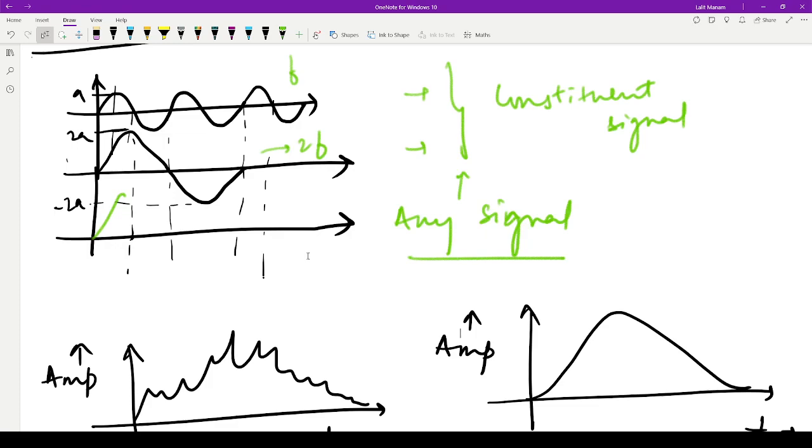Sir, I have a question. Do these frequency definitions change for different signals? Let's say we have an image and we have audio signals. These definitions are not so concrete: what is frequency in an image? It's actually the same. It's just that the independent axis changes. For audio signals, the signal generally varies with time, so you check frequency with respect to time. But for images or anything else which varies with space, you check frequency with respect to space, how the signal varies with respect to space.